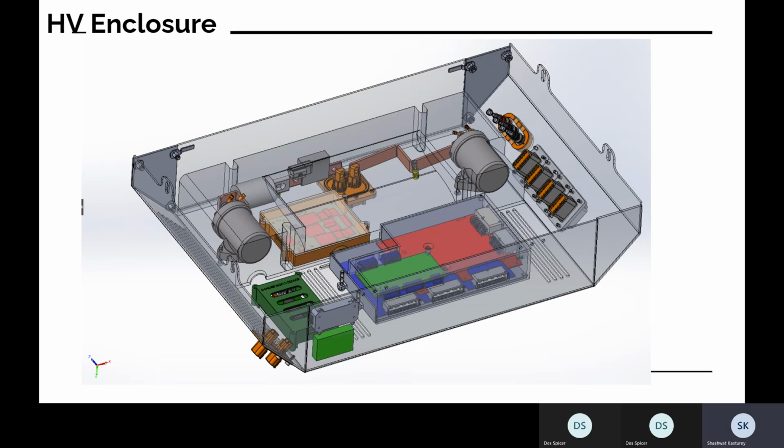There was actually a lot of debate on how we manage the car knowing if a fuse has blown, because it's too quick an event, on the order of milliseconds. Most temperature sensors have too slow a response time. The voltage, however, does not.